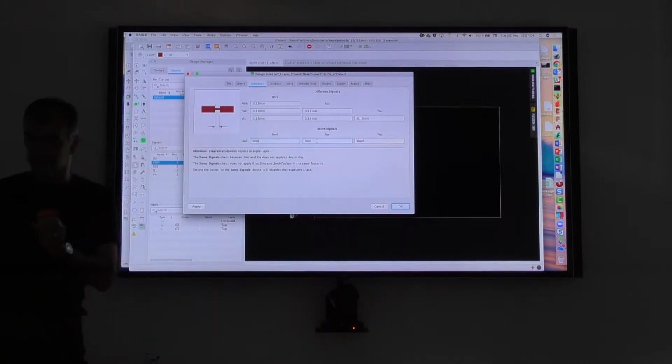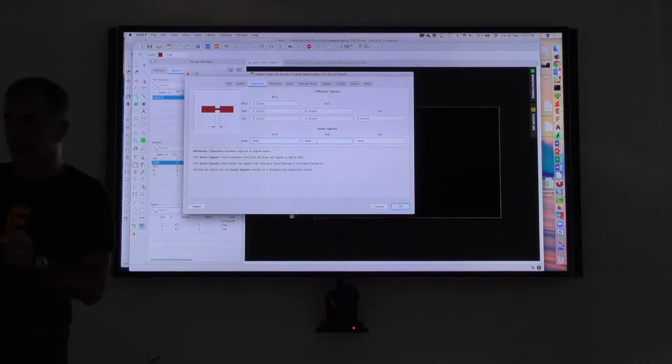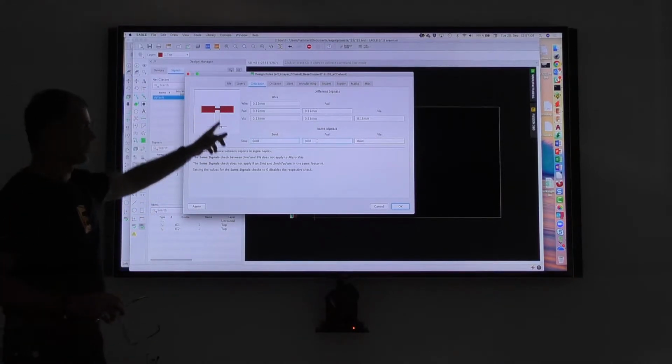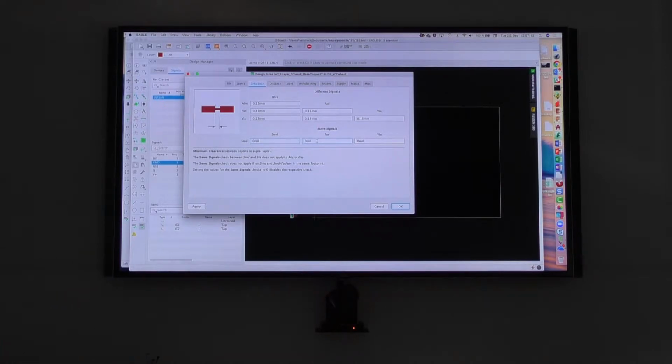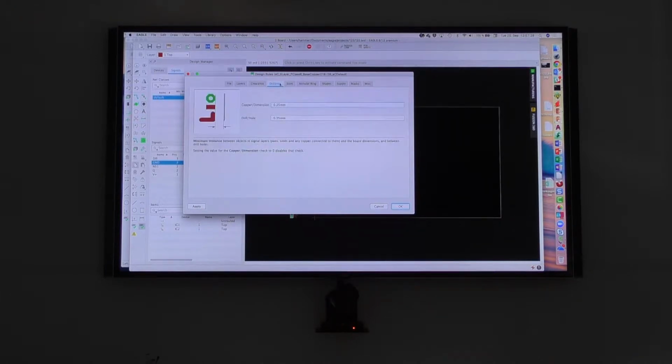You want to have some space between. Usually there's some solder stop over this trace so you don't get the connection there directly. So it's a secure way to solder this stuff. That all goes too far now, but it's really not so easy. And I'm surprised how many boards work if you see how they're done.